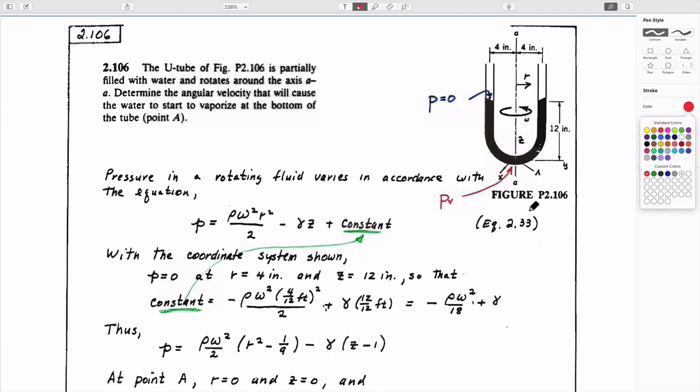And so the idea is to be able to suck it out of the Tygon tube, it must have a pressure that's low at the center of the tube that's pulling it out, because at the end of the tube where the fluid is, it has to be physically at atmospheric pressure. That's what we're feeling around here.